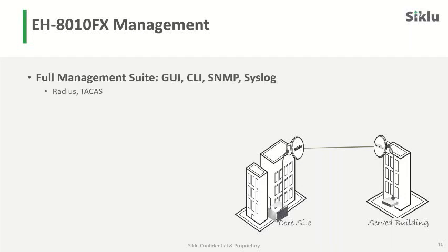So first of all, obviously, you know all our EtherHaul radios have a built-in web server which allows basically end-to-end graphical management of a link, but there is also a command line interface, SNMP, syslog. All these are still available on the 8010FX, no changes. And the user rights can be administered locally in the radio or centrally with Radius and TACACS servers.